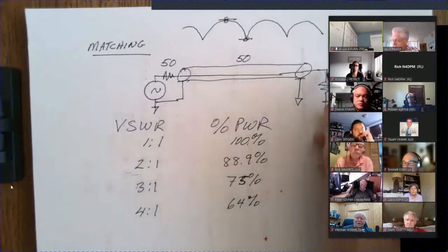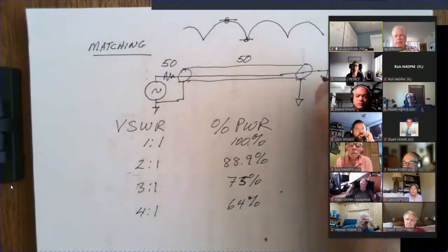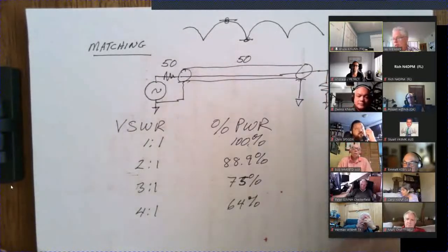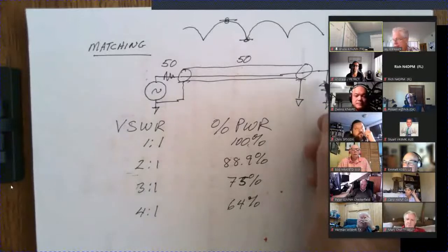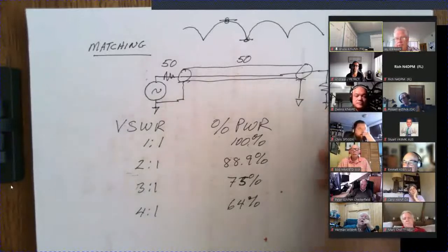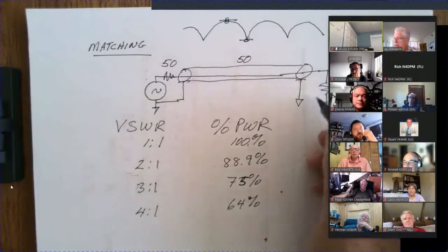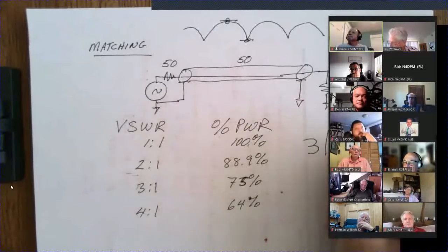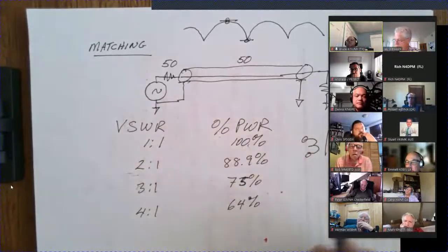The gentleman has suggested, why don't we put a balun in here? That would be an easy thing to do. But remember, it only works well if your antenna, first of all, is a resistance, and secondly, if the feed point impedance, which we're going to go back and talk about now, happens to be the right ratio. In other words, basically you have a transformer, and this is not necessarily how it's formed, by the way, but essentially this is what it looks like.